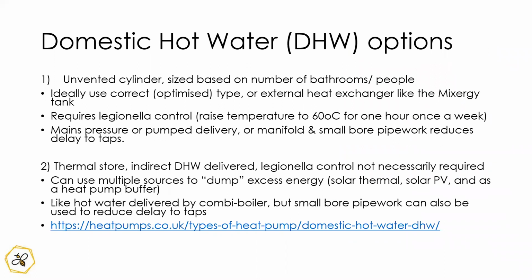John Cantor's website goes into this in a little more detail, with some calculations and some simple experiments at home to determine your hot water demand and habits. But essentially there are two options. You've got your unvented domestic hot water cylinder, and that's generally sized on numbers of bathrooms or people.